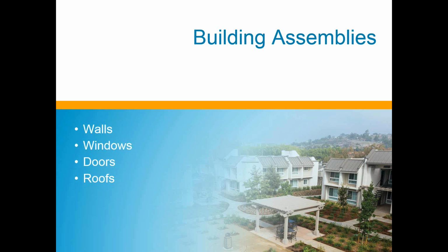I think the exterior is easier to install, and you get better coverage on the exterior because you don't have interior walls in your way. There are some products where the drywall is basically the insulation, aerogel, I think it's called, and I've seen that used in some high-rises where you can't do the exterior. I would have to think through the physics offline, but I think the exterior is going to be the best way to go, irrelevant of the climate.